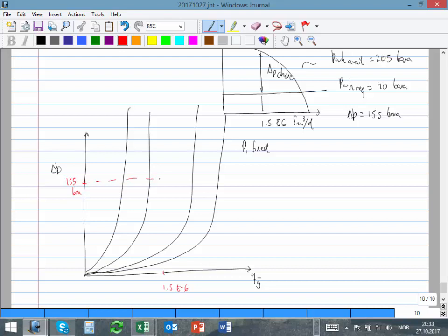So that's actually what we are doing with this equation. We have multiple curves. For example, the one that was initially half an inch, 0.5 inch, was here. That one will give me a different, much lower rate, 400 e to the 3. If I use a bigger choke, I'm going to get a higher rate, like for example a 2-inch choke will give me a higher rate. So I have to put the curve exactly where it gives me what I require.